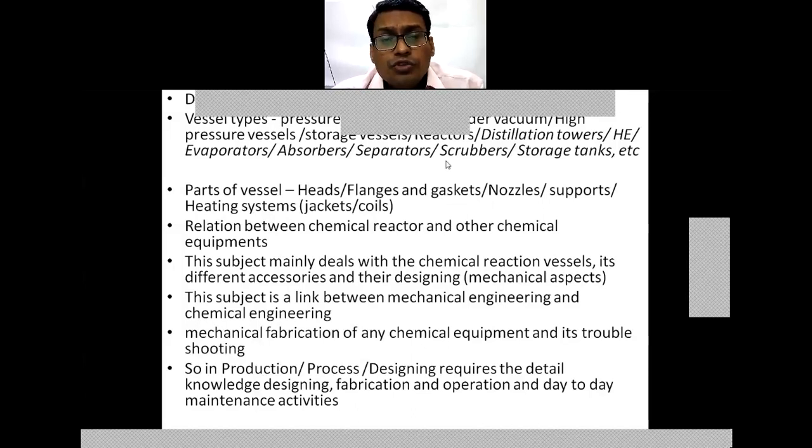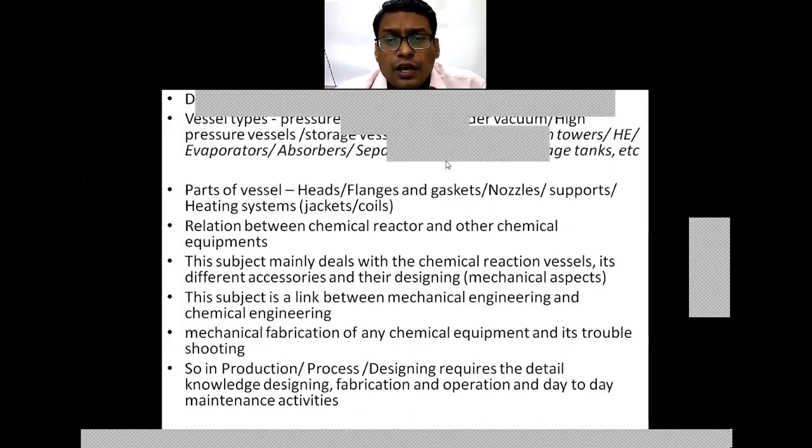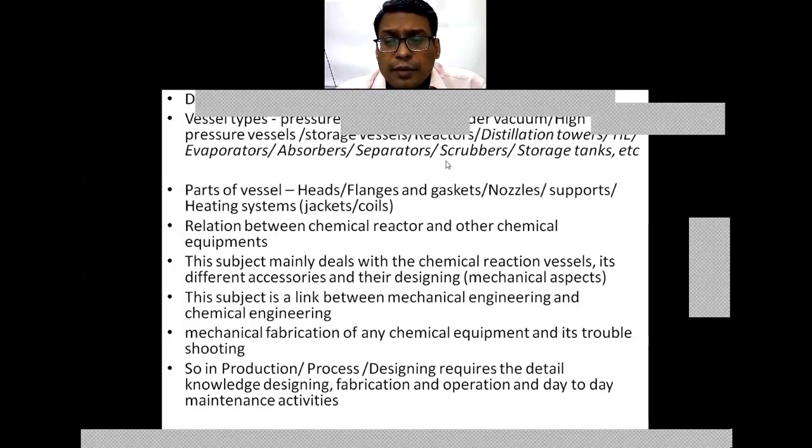You should know the different fabrication techniques of the vessel, and how, operation-wise or maintenance-wise, what the basic requirements are. So flange leakages, some damage in nozzles, then support systems not being better. In addition to that, whatever the design or whatever the fabricated equipment handed over by the mechanical engineer, its performance, whether it is proper or not, has to be properly evaluated by the chemical technologists.